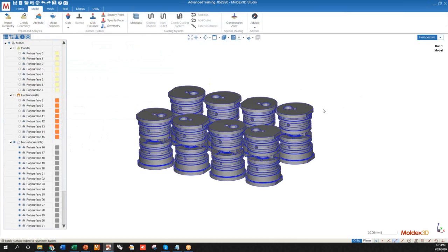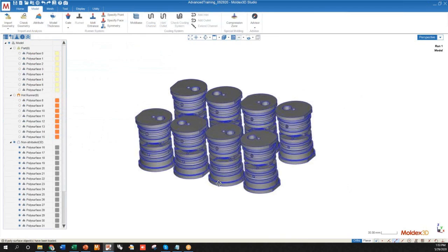Now you could designate those as you will, and you can import them separately to make sure that you have your material group separated and all that good stuff. But just to show you that you can import these as the same material or the same step file, and you can import multiple step files at the same time. We just brought them all in at once.